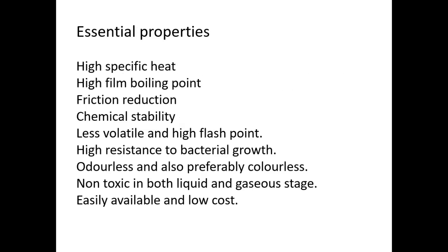The first one, high specific heat, high film boiling point, friction reduction, chemical stability, less volatile and high flash point, resistance, odorless, non-toxic, easily available and low cost. These are all the essential or desirable properties of a cutting fluid used in machining operations. All such cutting fluids used in the system must have these properties.